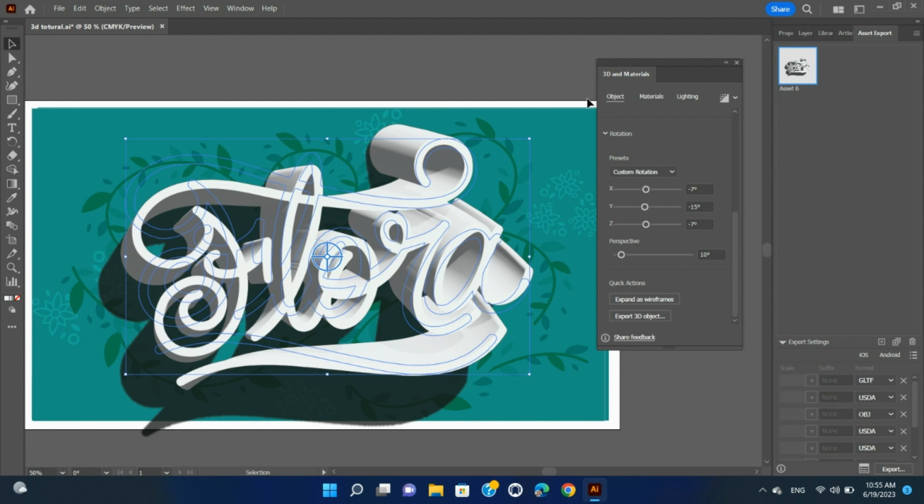Export 3D objects. You can export 3D objects to GLTF and USD file formats and open them in other 3D applications to further edit and enhance 3D objects and 3D objects with materials and graphics. Illustrator also supports exporting 3D objects as OBJ files along with colors. When you export multiple objects, you can view each object as an independent modifiable object. Follow the steps to export 3D objects.